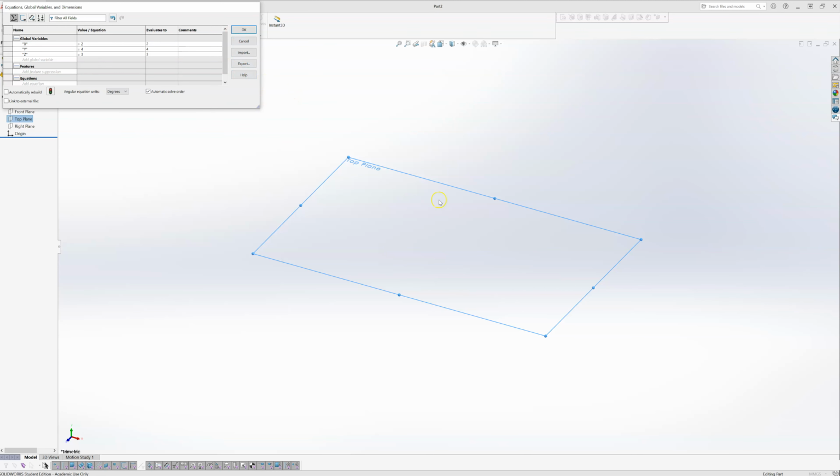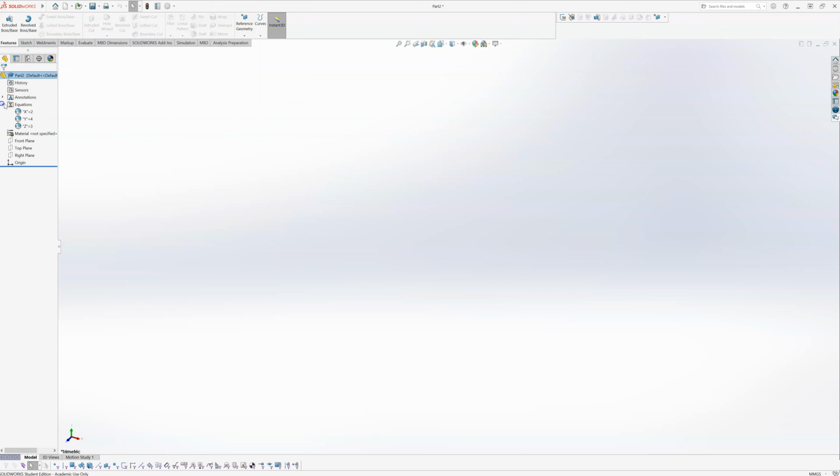Okay, so when it comes to dimensioning my model, I can just refer back to these variables. Remember, these represent the number of Lego units, so the block is going to be 2 Lego units in the horizontal, 4 Lego units in the vertical, and 3 in depth. I'll OK that, and you should see this category appear in the feature tree for my x, y, and z variables.